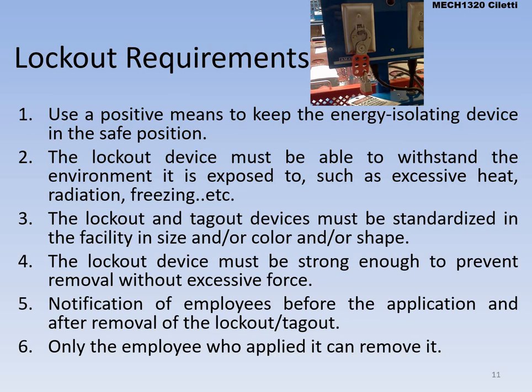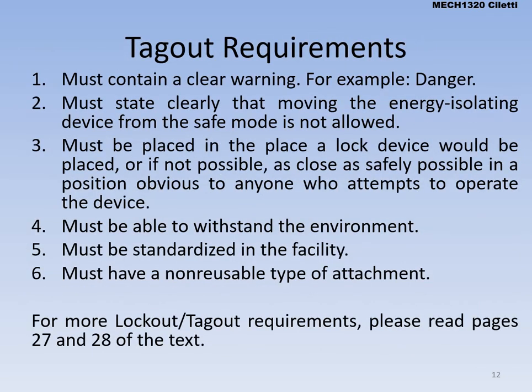Okay, and the most important thing, and I've already hit on this before: the only employee that can take the lockout tagout off is the employee who applied it. Only you can take off your lock. Only you have the key to your lock. I know in certain companies it may be a little different, but this is just in general how it goes. And it's very important safety when we're talking about mechanical devices that can crush you, hurt you, tear you.